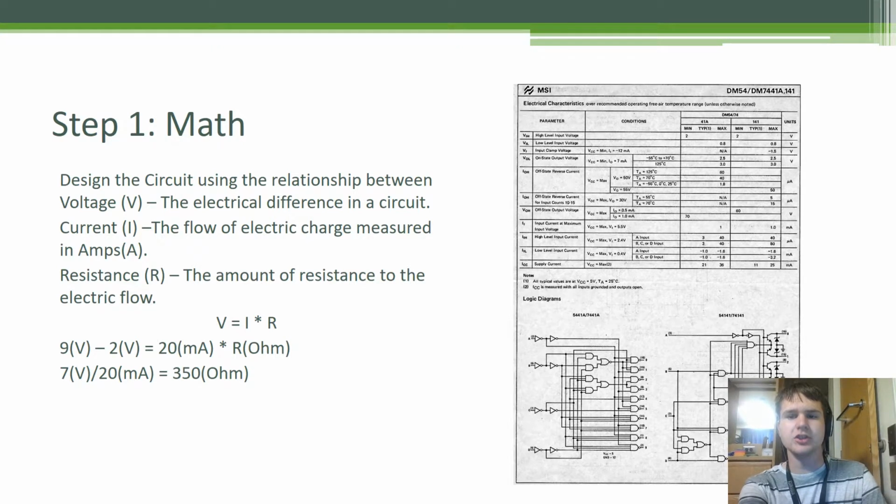As a side note, the voltage must be exact for the specifications of the device. However, you must simply have at least the amount of current that the device specifies. For this circuit, we'll be powering an LED, and according to the data sheet, we need to provide 2 volts and at least 20 milliamps.